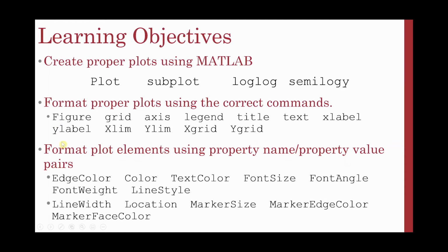We're going to learn how to format proper plots using the correct commands. We have figure, grid, axis, legend, title, xlabel, ylabel, limits. And we're going to format plot elements using property name, property value. So we're going to learn how to use edge color, text color, font size, marker size, and more to edit some looks of our graphs.